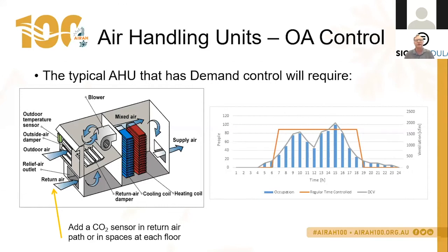You can see in the graph there, it would just be open. The outside air will be open and operating based on just the on-off requirements of the system, and then switch off at a certain time. With the outside air economy cycle, the CO2 control system will respond to the CO2 levels within the space.